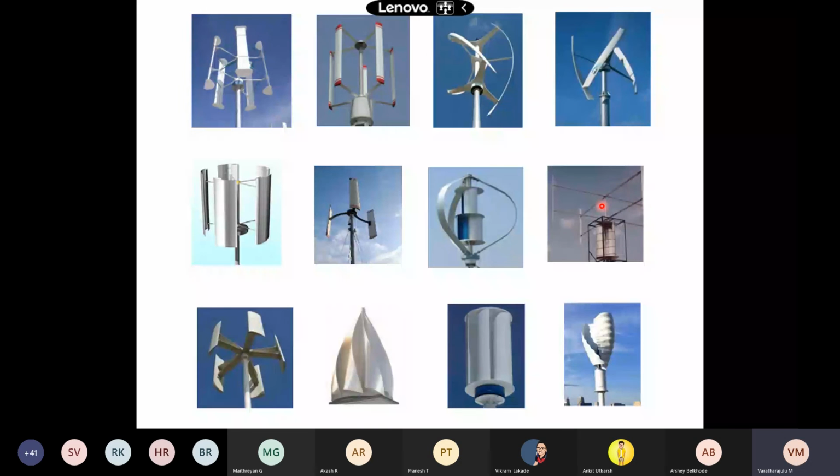Therefore, this flywheel arrangement, this driving mechanism, leads to having power even when there is a drop in the wind velocity. The issue with this structural arrangement is that the initial torque should be maximum, because this system has a very heavy arrangement. Therefore, the initial velocity of the wind should be higher.